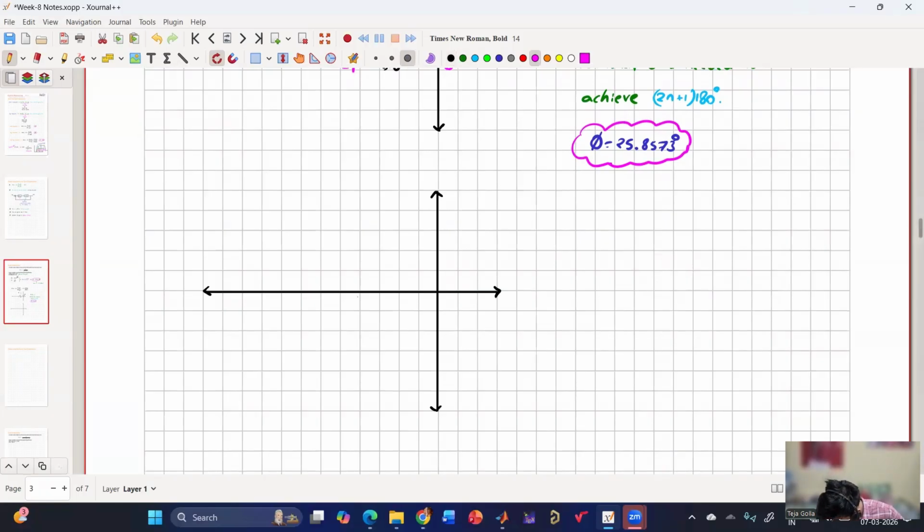is close. Say this is my zero, this is my pole, and say my closed loop pole is somewhere here. So now this is my phi, right? This is my phi. And this is my phi. So this angle will be phi. And then I can call this angle theta and then this angle gamma. So my phi is fixed and theta is also fixed.